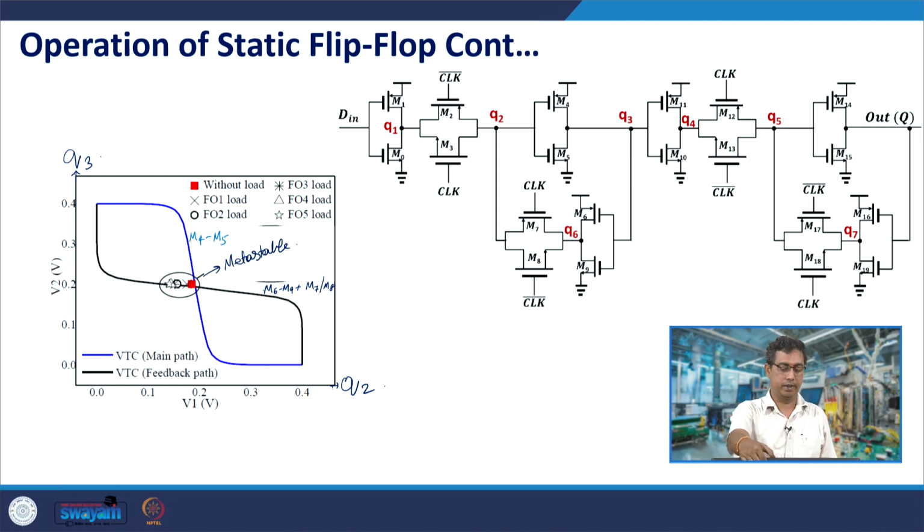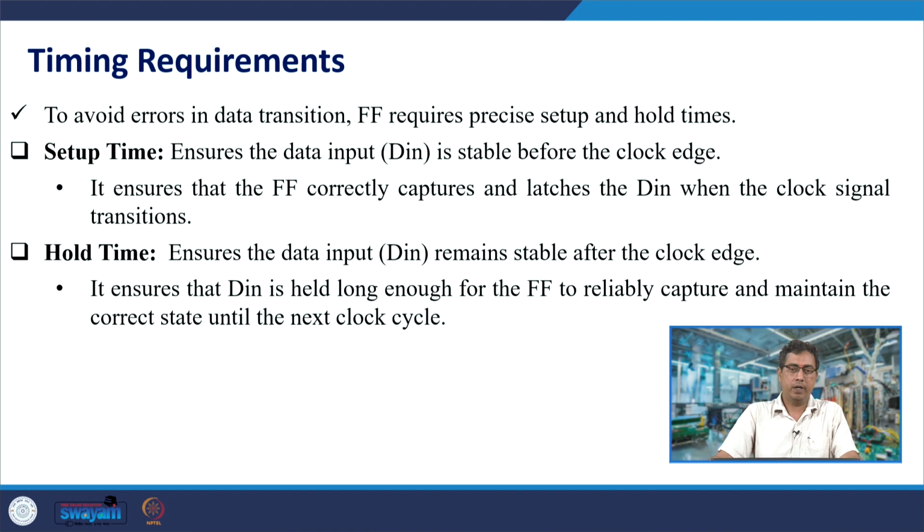We will discuss further. This metastable point becomes important if you violate the setup time or hold time of the flip flop. So, what are the setup time and hold time? The input data, as you know, should be available sufficiently before the clock.